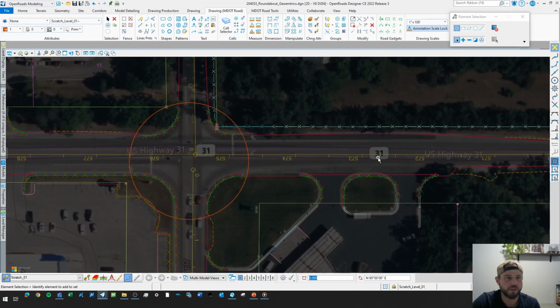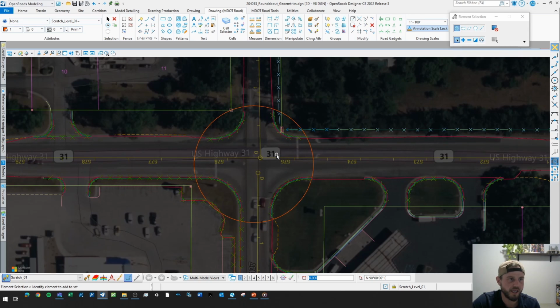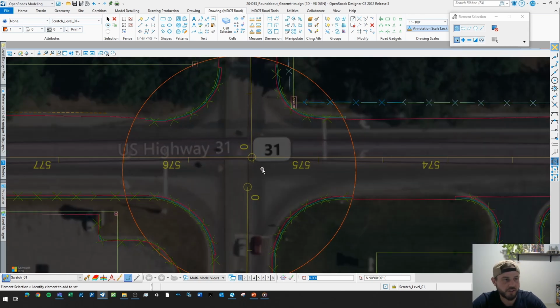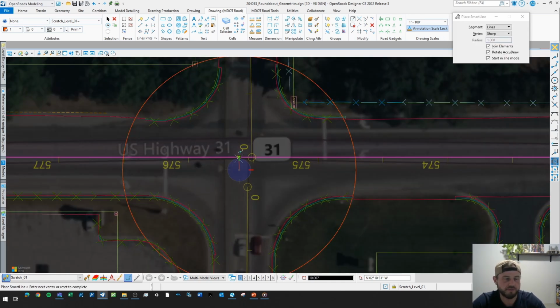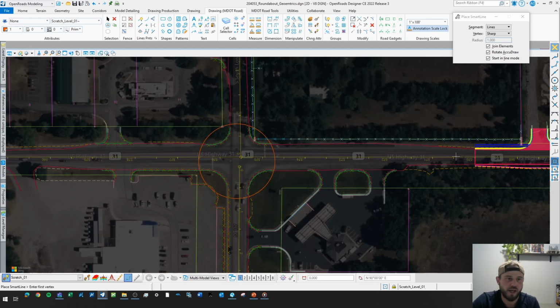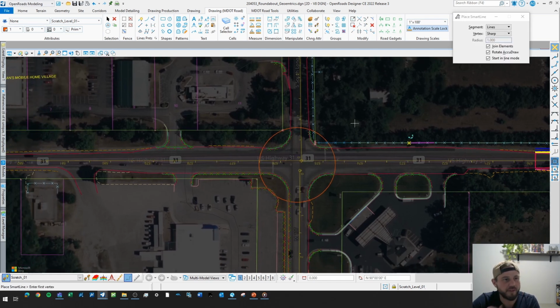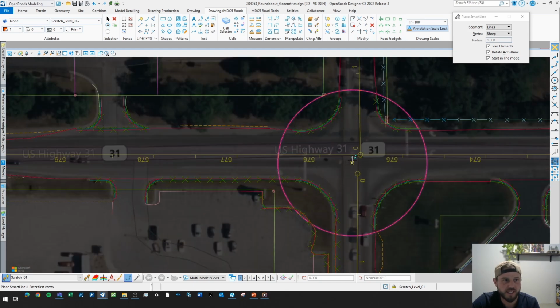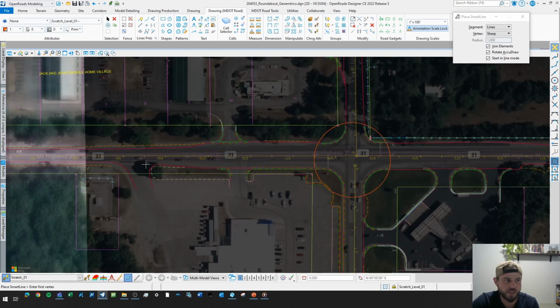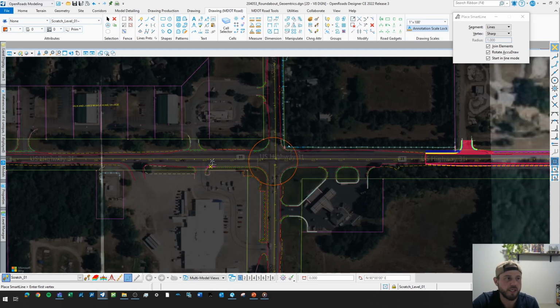So with that, as you're going westbound, this alignment is going to be to the right of the center of this ICD. So I can see already just from knowing that this alignment is going to have, this roadway is going to have to curl down a little bit as it comes in to get the deflection that we're going to be looking for. On the other side of things, for eastbound, this alignment is on the left side, so this one's already kind of in pretty good shape.